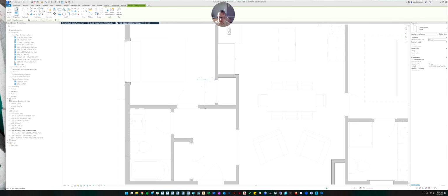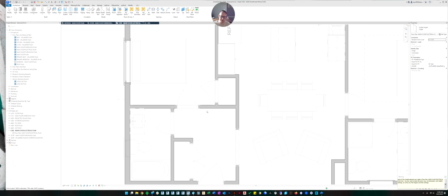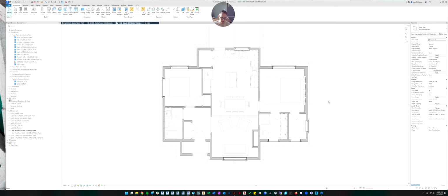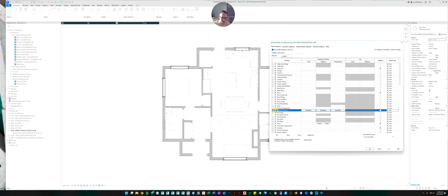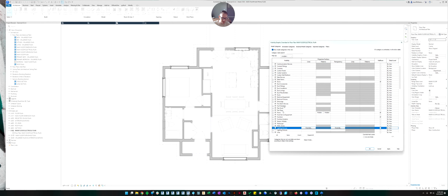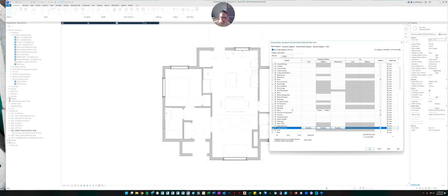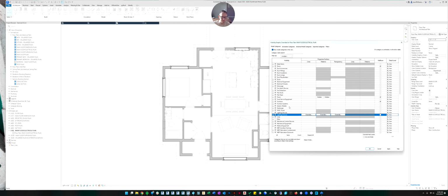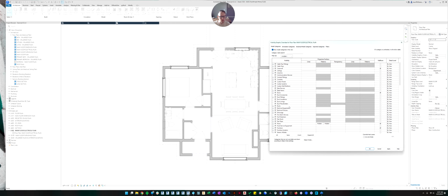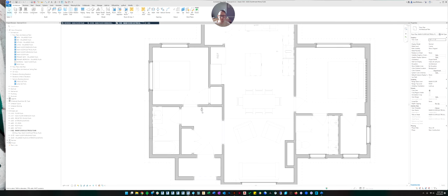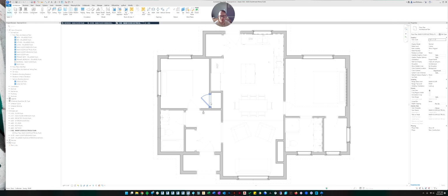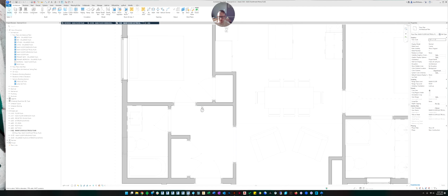And if I click, oh, it looks like it's not showing in this view. So let's go to our visibility graphics and make sure we have electrical fixtures on. What about lighting? Lighting devices and lighting fixtures, we want those showing. Yours should probably already be checked. You probably won't have this problem. It might just be me. Yours will probably have just done this. I made some settings in between videos that you wouldn't have made, so I accidentally shut off the electrical outlets. All right, let's go back to placing.